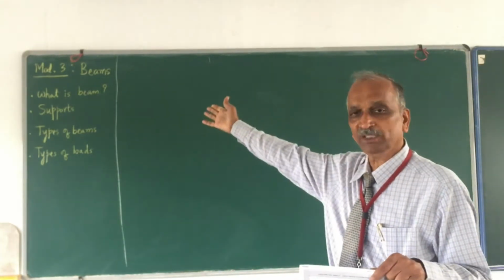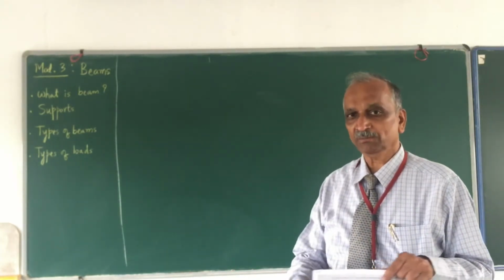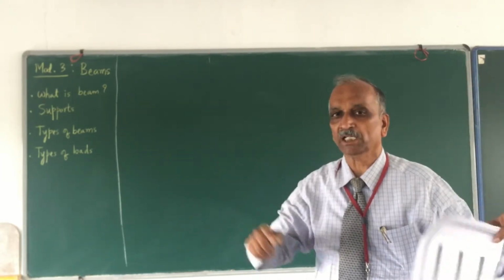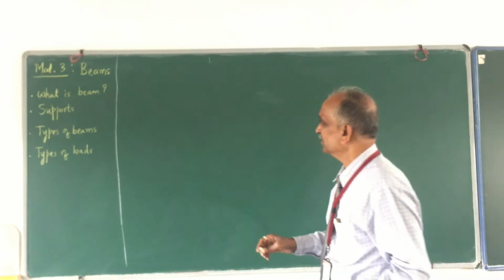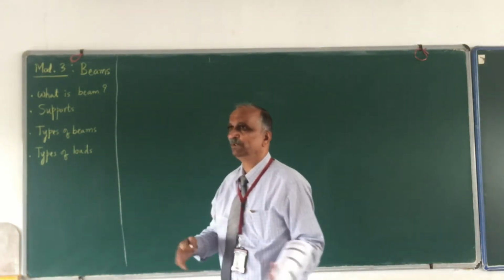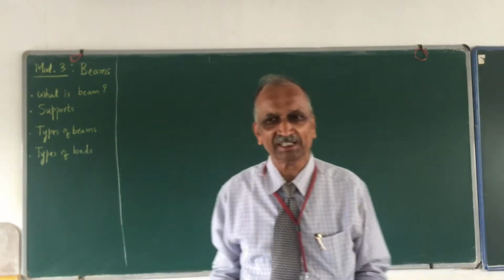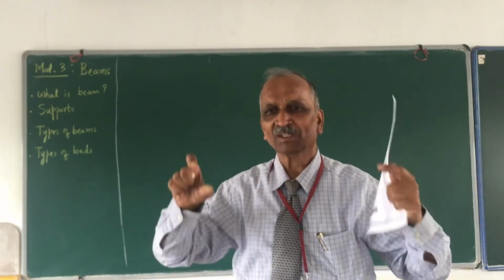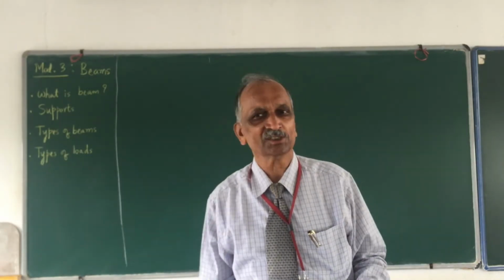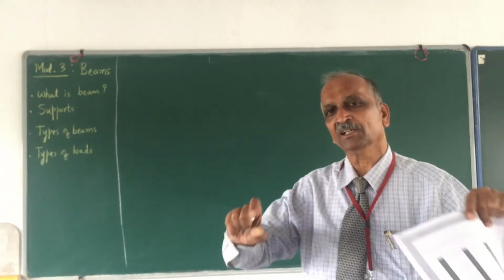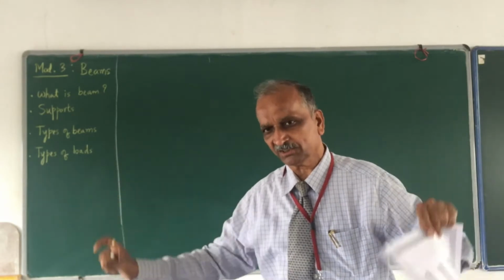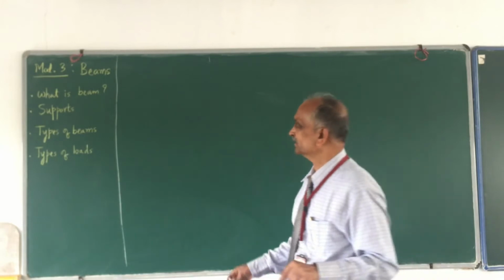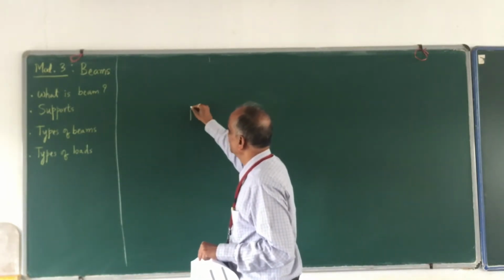That is why we now have another case, the beam, which is a member subjected to loads perpendicular to the axis. A beam may be horizontal, vertical, or inclined in any direction. Many times, the moment we say beam, we normally draw it in the horizontal direction. Don't be under the impression that a beam is always horizontal, not necessarily. It may be a vertical beam also, it may be inclined. But I shall draw it, say, something like this, a member.